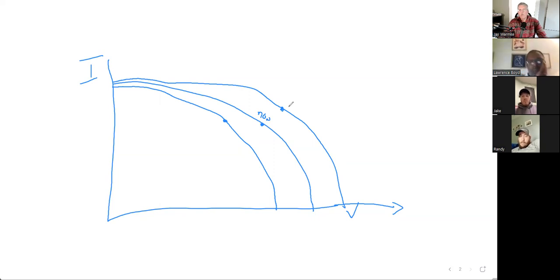Well, let's say it gets colder. At my MPP, maximum power point, it might actually be up to 75 watts, but it's not at the VOC. It's still at the VMP, but the VMP has increased. So you're going to operate at the VMP for voltage all the time, and it can exceed the nominal voltage of the panel, the rated voltage, because this voltage or this wattage is all determined at STC. So the colder it gets, the more power it might produce.